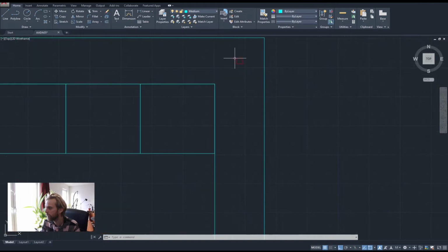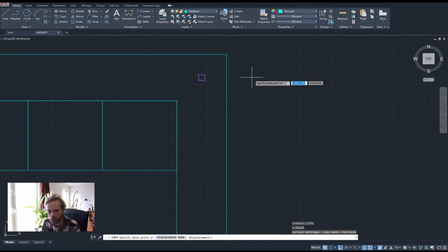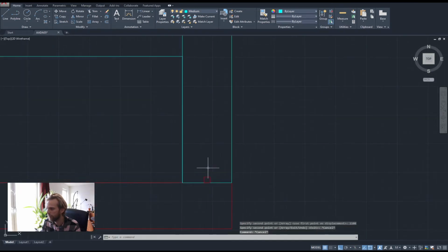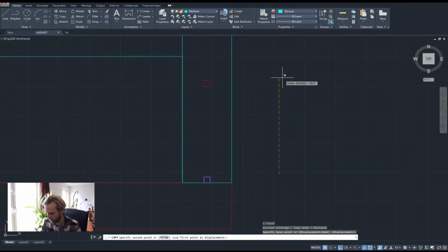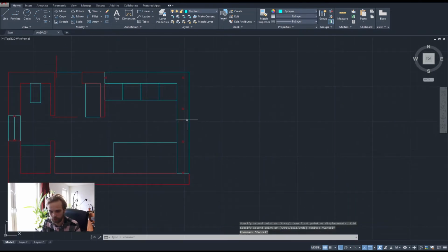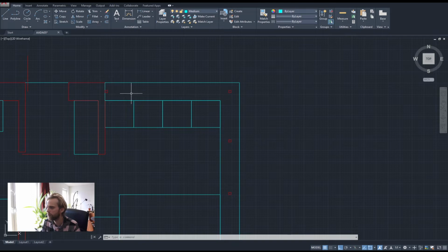So what I'm going to do is take this frame and copy that frame cut downwards by 1.1 meters, like that. And I'll take the bottom frame and copy it upwards by 1100, enter. Escape out of the copy. So now I have a pretty okay transition here. And also, I believe we do want at least one window frame here in the middle.